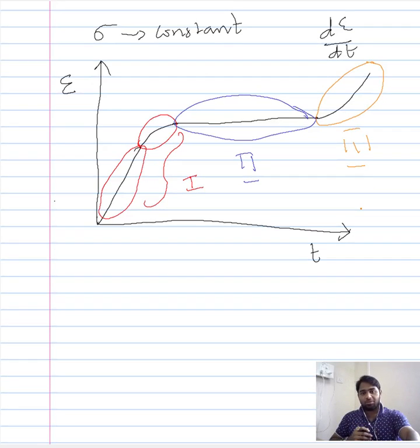The reason why I say that it is just one of the ways is because in this creep curve we have a region called the instantaneous creep region. So this region here, let me make it even darker, this region here is the instantaneous creep region. Now, this instantaneous creep region is brought about in this curve by the load that you impose on this system. So, unlike tensile loading, wherein your load will gradually increase with the strain, in creep you suddenly impose the load, and the immediate change in the strain is shown by this instantaneous creep.